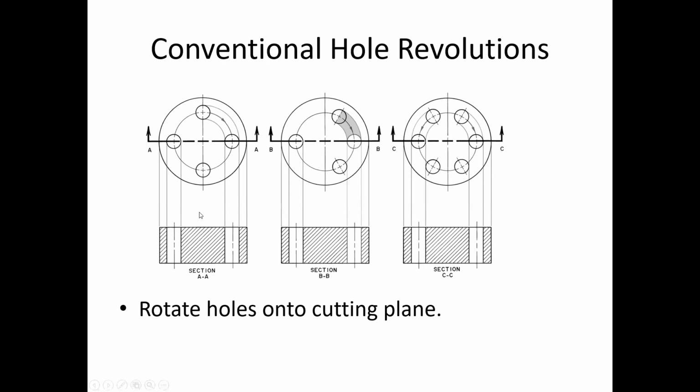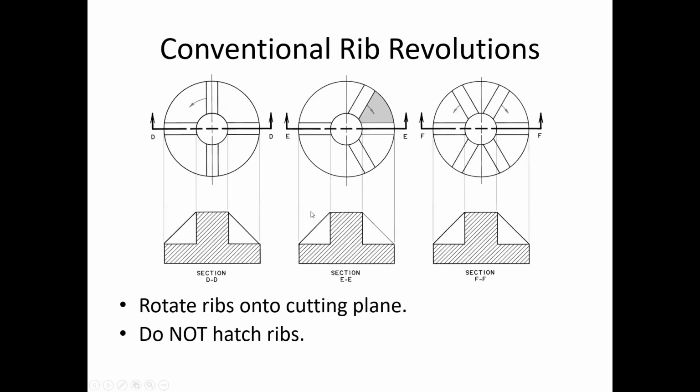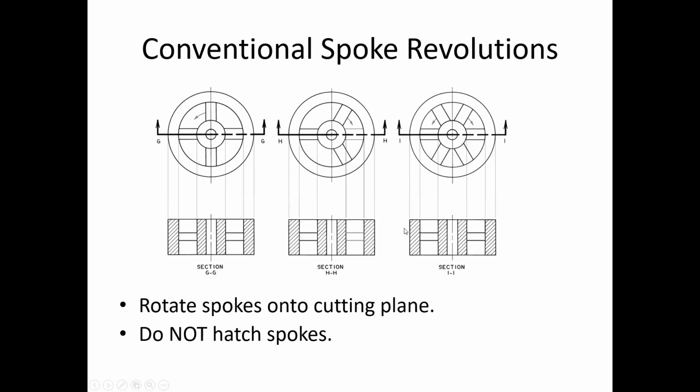Yeah, so you're talking about the center. I would personally like to see the center axis on all these, as well as this one. I can't really say why these images on the slide are like that. I would like to see center lines in them. Anytime you have a hole or a circular material that has an axis through it, I'd like to see the center lines, whether it's solid or a hole.